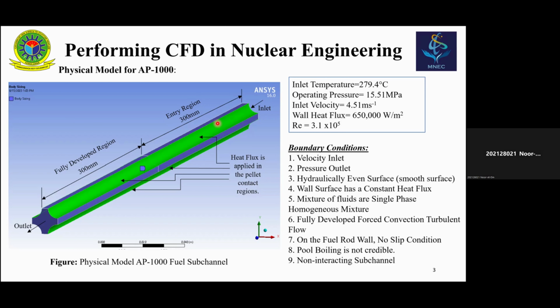Why? Because if water boils there, bubbles will be formed, and these bubbles will damage the cladding material properties. Yes, this can be, and it will lead to various destruction, like increasing the criticality and everything. So we cannot let the water boil. And non-interacting subchannel, you will understand this boundary condition later.